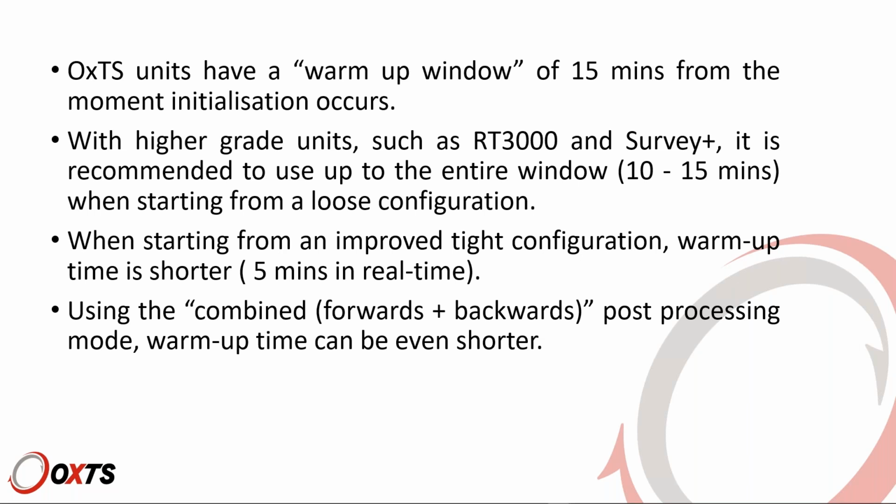If you are doing the calibration run, the one upon which you will base all of your settings, then take your time, and I would recommend you take the entire 15 minutes. If you are processing in combined mode, more on this in a bit, then the warm-up can be even shorter, because the two traces, forwards and backwards, will help each other in improving the accuracy.